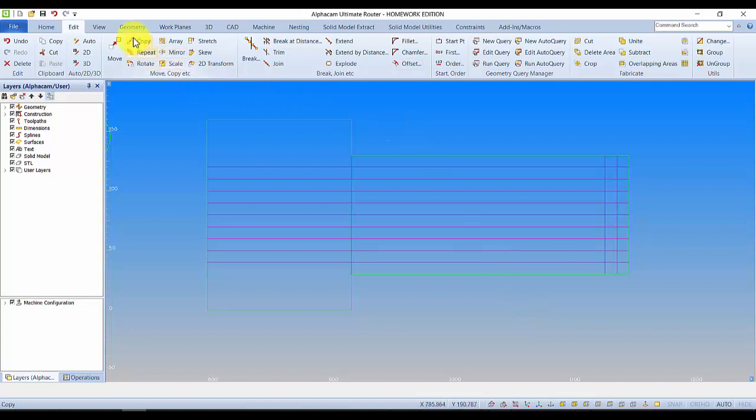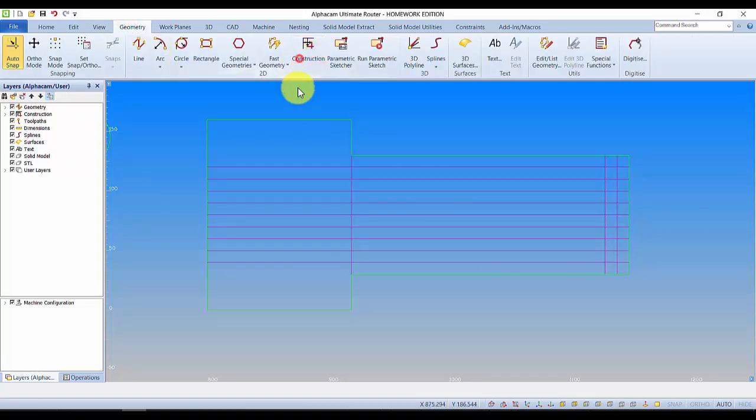So what I will do now is call up geometry, turn off construction, call up a regular line, and I want to snap and draw a couple of rectangles. In fact, I will do a rectangle instead of a line, but I want to snap to that intersection between those two lines. By default, it always tries to snap to midpoints and endpoints. So I'll turn on snap to intersection. That should allow me to pick up this point. When I click this line and that line, it should snap to the intersection between them.